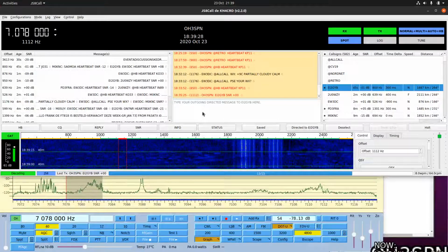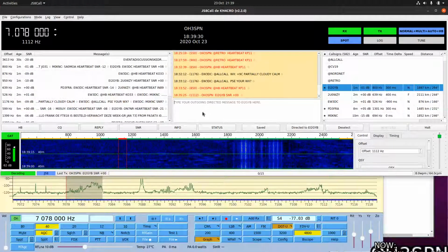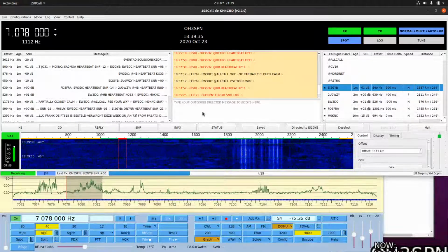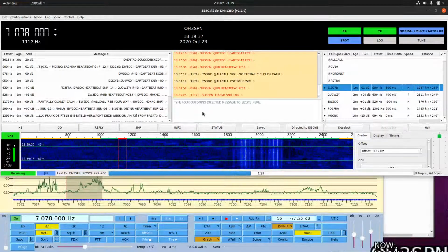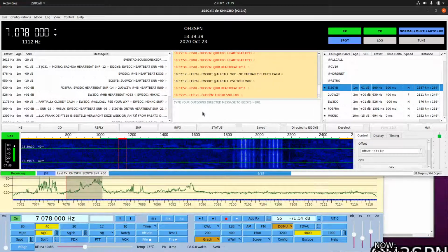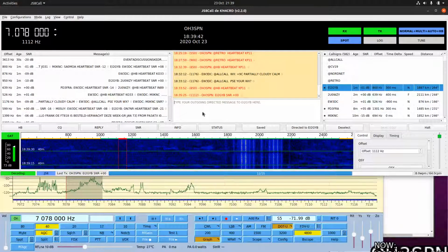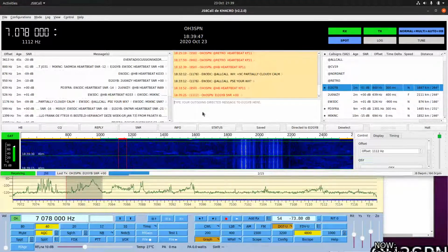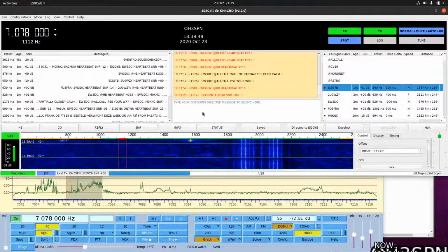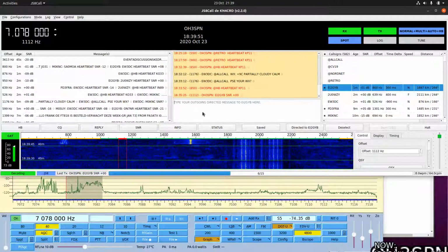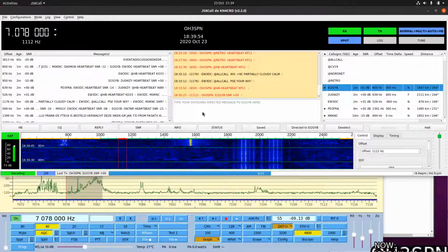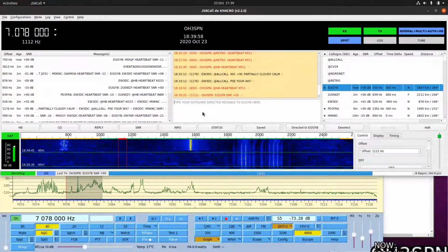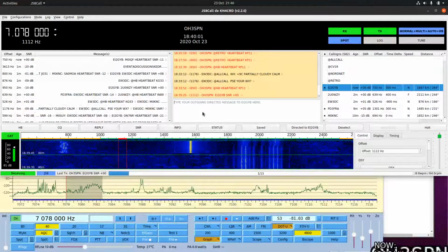So I'm lucky here. I'm in the middle of Finland. I can have my RF gain on maximum and I have nothing reading on my S meter, which is how it should be. There is a noise floor, obviously higher than the receiver noise floor, but when I disconnect the antenna and attach the antenna, there's an audible increase in noise, but no indicated increase on the S meter. I haven't really looked at the spectrum scope on the 7300. That's interesting, actually.